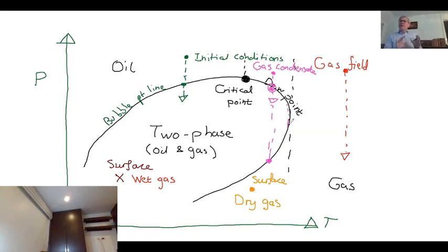And then people often say, okay, but how do I know what it is? Well, remember, this phase diagram, how do you produce this phase diagram? It doesn't appear by magic. I've done a schematic here. You take fluid samples from the reservoir from discovery, and you measure this phase diagram in a laboratory. I mean, I've just shown you that you'd have a little cell and you vary temperature and pressure, and you'd see where you had two phases and where it's a single phase.